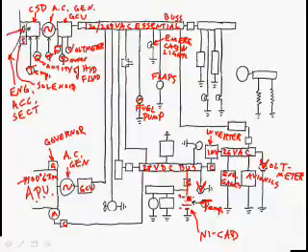Let's see. Hot battery bus. Look at this. Right coming off of the battery straight into here. It's hot all the time. There's no way to turn it off. Hot battery bus. And of course, on a transport category jet, big biz jet, big turboprop, big turbine powered helicopter, we might have things other than a Hobbs meter. On this Boeing 777, the APU fire protection system is on the hot battery bus, so even if we have full electrical failure, we can still use the fire protection system for the APU.